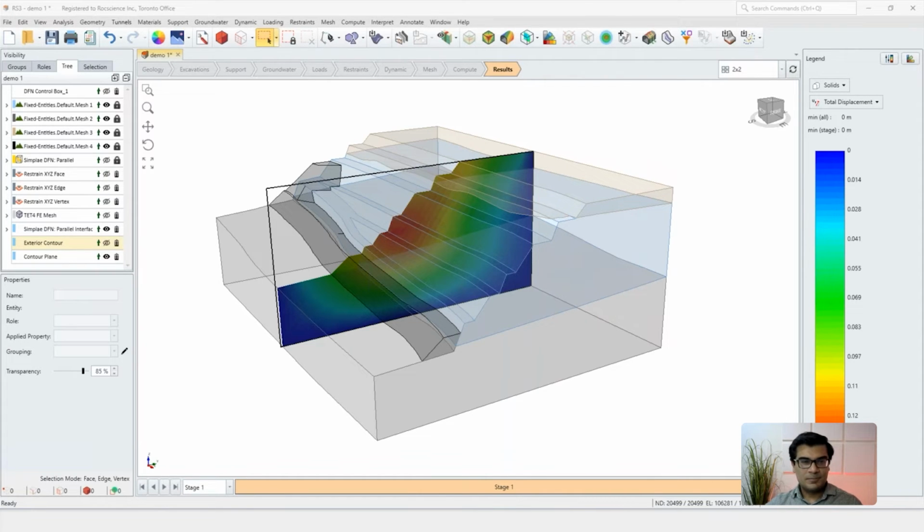Just one more, then you can continue. Within the flow of creating this model, when is it recommended to add the DFN to the system? That's a very good question. As long as you have an external volume in your geometry, you can assign the DFN. But the best time to do it is when everything else is already defined: you define all the other volumes, you did all the divide alls for them, you assigned all the cutting planes.